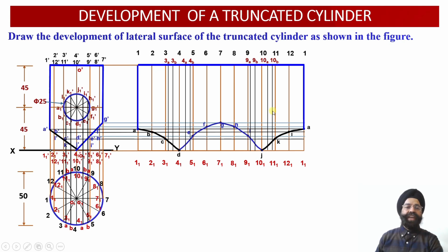So this way we have identified onto these black color projection lines which are corresponding to the intermediate 8 points over here, these ones and these ones over here. So which points they are going to lie on which vertical projector line over here. So now let us evaluate the location of the 12 points corresponding to the circular hole onto the front side of the circumference and the 12 points corresponding to the circular hole onto the rear side of the circumference of this hollow circular cylinder over here.